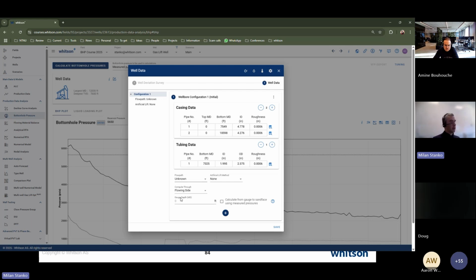And then here we say flow path. We're going to have flow path through the tubing. We're injecting gas through the annulus. So tubing, artificial lift. Here we're going to say gas lift. And the configuration we will use first is point of injection. But we already mentioned we have these three. We have reverse valves, we have valves, and we have automatic. Let's for now use injection. Remember, this is injection at the end of tubing.